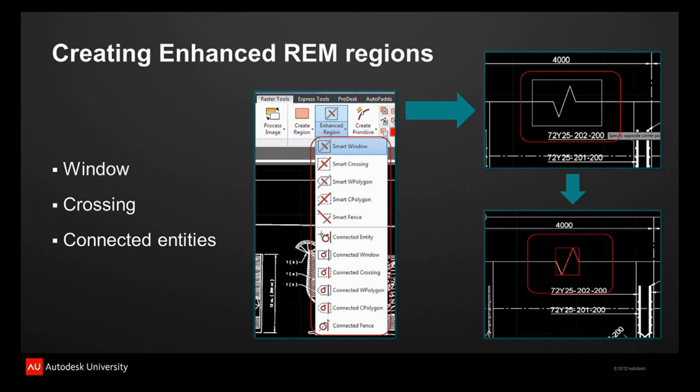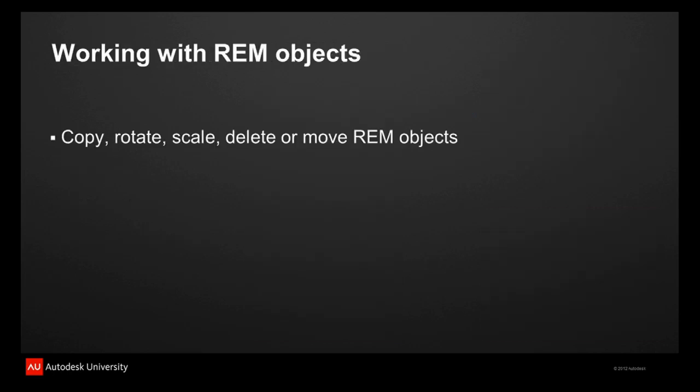The first one I used here was Smart Window, and basically what this does, you'll see there is the window that I created. So within this red area, that white square is the window that I created using Smart Window, and that is my selection. So even though the window crosses those horizontal lines, it obviously didn't include them. This only included the objects that were in that selection, like a box selection. You can also use cross selection. You can use Smart Pick, where it tries to identify a continuous line or element that is continuous.